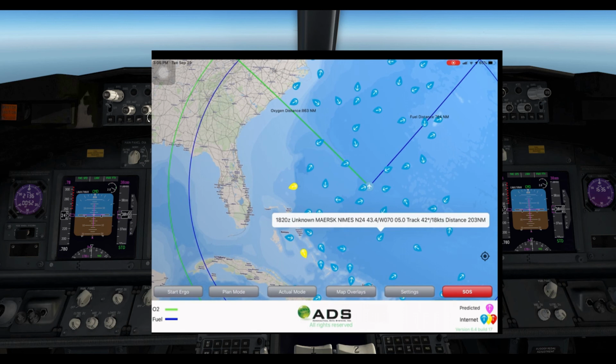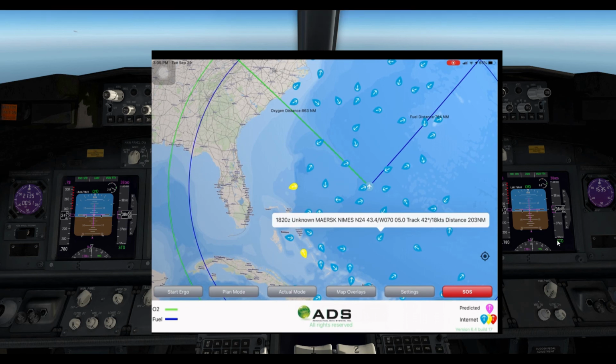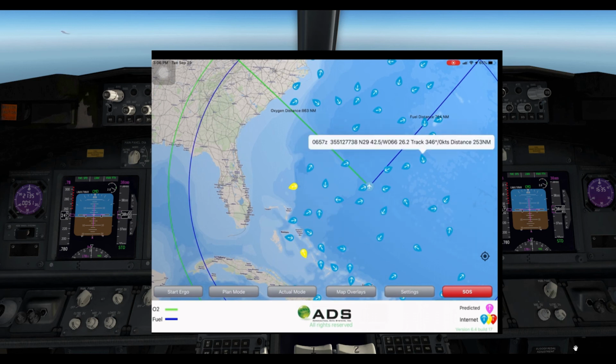Once this message is sent over the data frequency, the handheld radio you are using will automatically change frequency to the maritime voice distress frequency. The next transmission will require the pilot to select a ship before the message can be sent. Once the ship is selected, the pilot need only press a confirmation button on the iPad, and no other pilot input is required from that point forward.